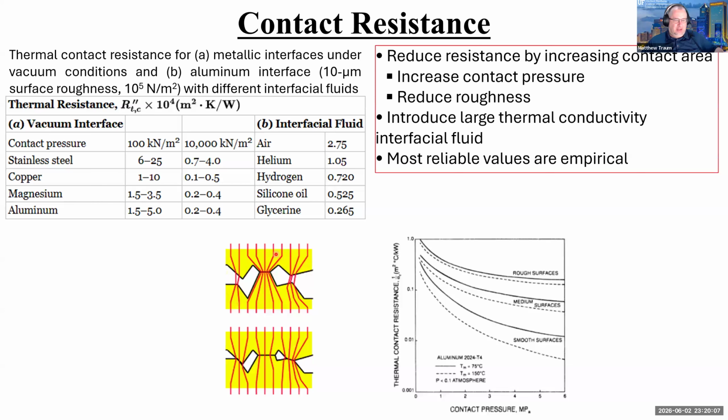This is a kind of low pressure situation where these two members are not being pushed together. And you can see there's a little bit of heat transfer between this contact point, maybe a little bit of radiation across this one and this one. But when you push them together, when you pressurize them, you close those gaps, increase the conduction area, and the heat transfer resistance will go down as a result of that.